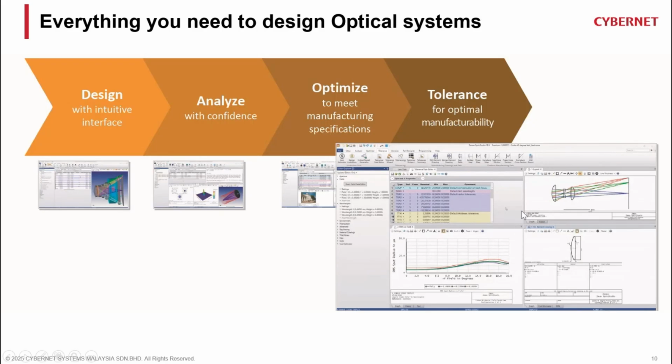Okay, so in these tools, we can simulate all these kinds of tilting and rotating or misalignment of the lenses and also the material's refractive index variation. So from here, we can understand how robust our system is, and whether we need additional modification on the design, and according to that we go back to the design to get a better image quality.